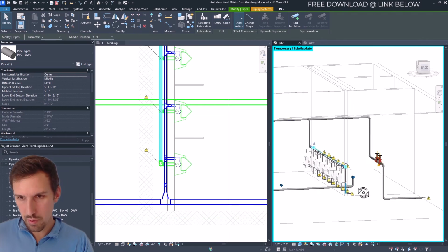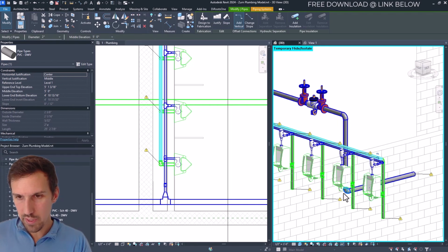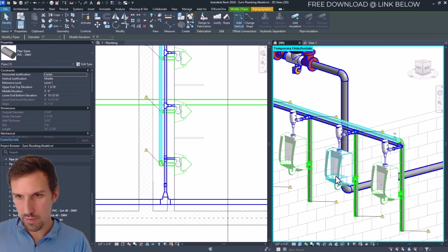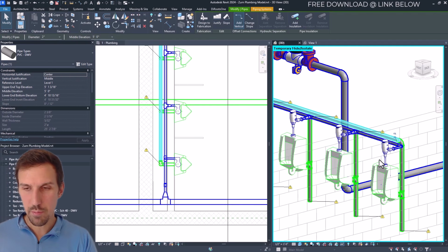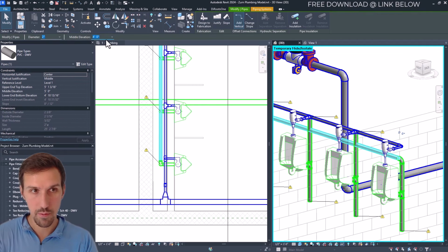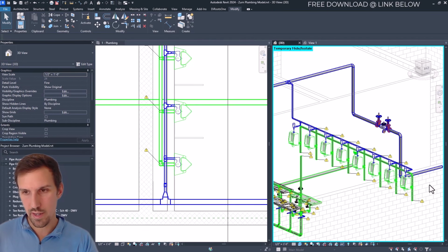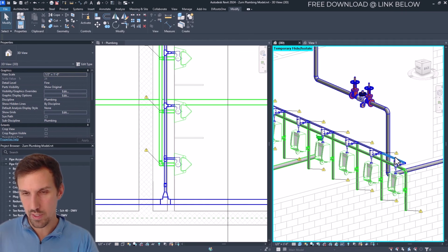Now I might want to bring my vent pipe up a little bit. It only really has to be 6 inches over the flood rim of this, so it really depends on where the contractor wants to put this vent. I think we could even make it shorter, so if we make it to like 4 feet, that brings our vent piping a little further down, so that's kind of nice. And then the water piping goes on top of it.